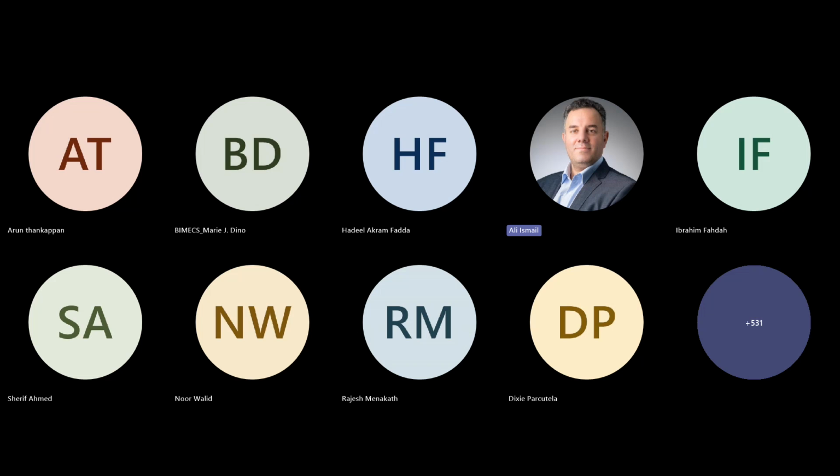So it's just like a parameter. This will help us to visualize these parameters and to check that the civil defense requirements are fulfilled. There is no calculation of the accumulated value of fire rating for finished material. This is a kind of input provided by the consultant, maybe in Revit as a family level or instance level parameter.